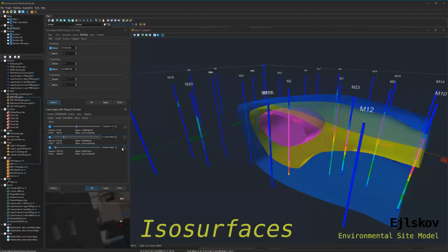Still, if we have access to the source areas within the site, but the remediation can only be performed within the site boundary, we would still try to aim at assessing the total soil mass that is present within the source, so that we can design the PRB with an idea of how much contaminant mass could hypothetically flow through the site boundary zone.